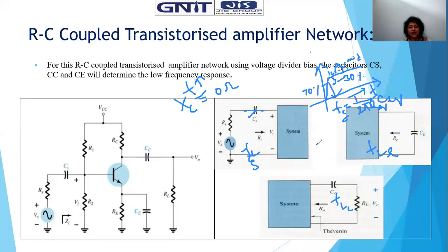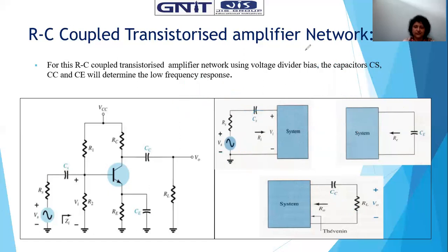So that's why I am analyzing all those cutoff frequencies one by one, with respect to CS, then CO, CC, and then C. Okay, so we are on the sketch and moving towards the next slide. But before that, with respect to CS, we have to know the equivalent circuit because we have to calculate the R equivalent, and then with CS we find the cutoff frequency, that is 1 by 2 pi Rs.